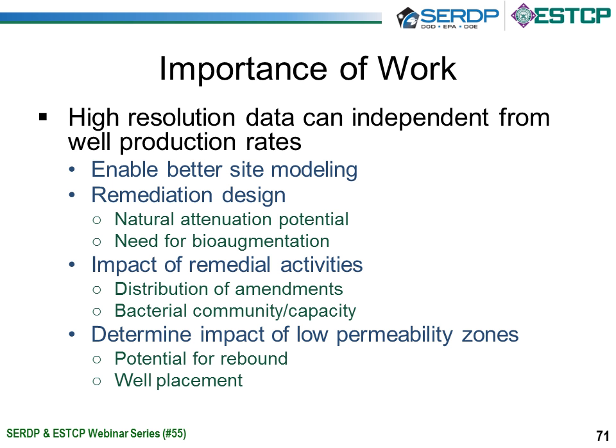The importance of the work, well, the nice thing that we think about this technology is that it's high resolution data, but it's independent from well production rates. So you're no longer dependent upon the hydraulic conductivity of the zone you're interested in. We think this should provide much better site modeling because of the higher resolution data.